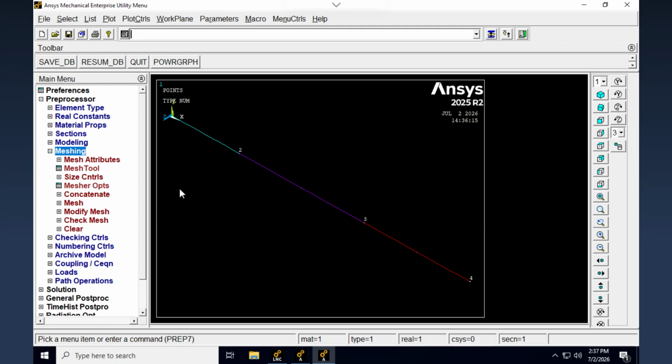If you guys want, you can do sensitivity analysis. Do 5 elements, then you can do more, and then see how much results change. Or you can start from 1 element and then keep adding more, and then you see if your results get converged. Right, so I'm going to do 5. 5 is going to work.